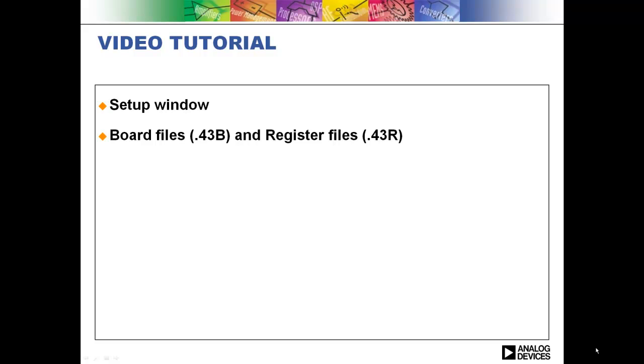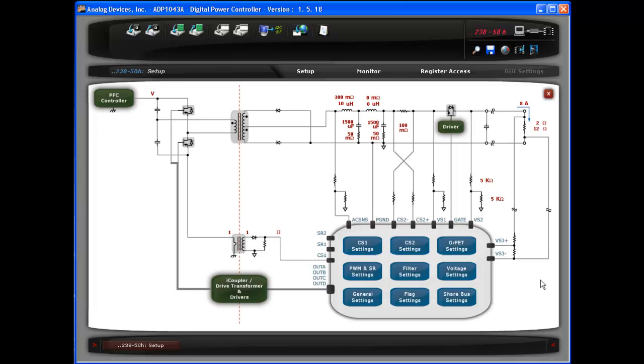In this video, we'll learn about the following items: the setup window, saving board files and register files, and programming the general settings of the ADP1043A. Let's have a look at the setup window.